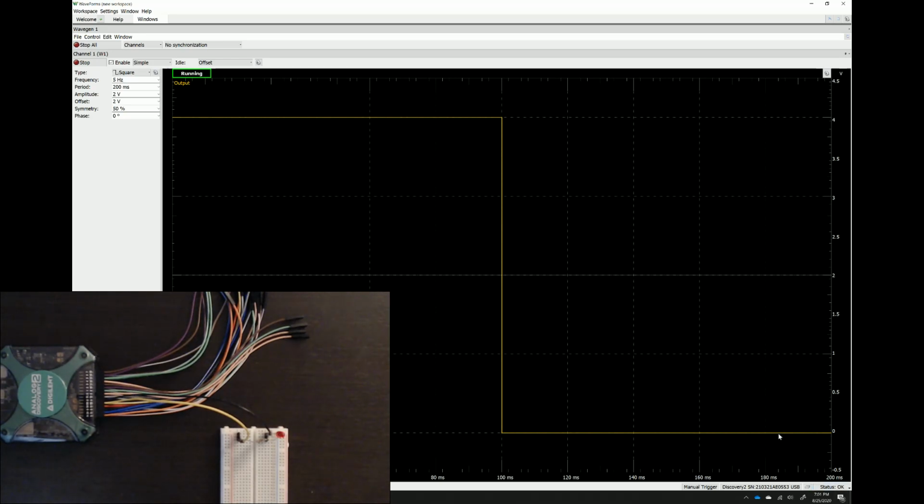If you continue to increase the frequency or decrease the period, you will notice that your eye can no longer perceive the difference around 60 Hertz. Similarly, the webcam cannot pick up these differences, but the LED is still capable of turning on and off much faster. The reality is that beyond a certain frequency, we're only perceiving the average brightness here. We can see this by modifying the symmetry parameter of our signal, which relates to the signal's duty cycle.